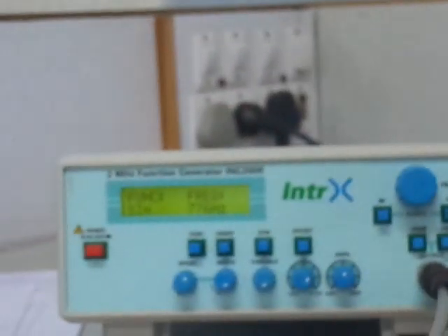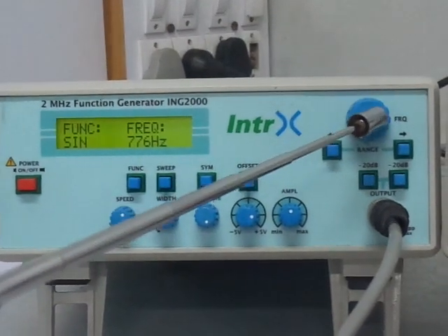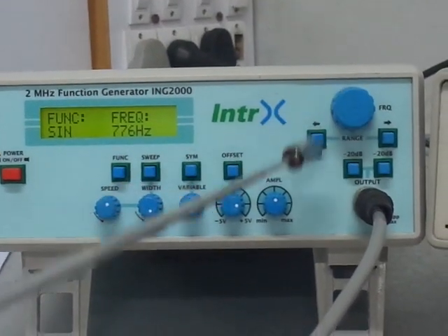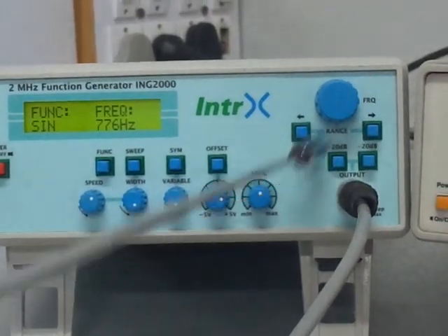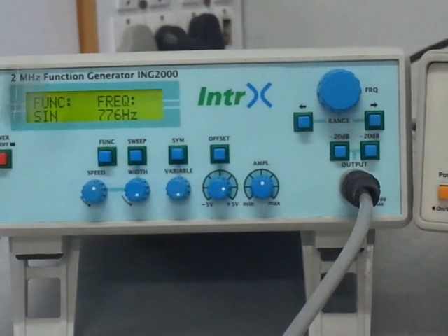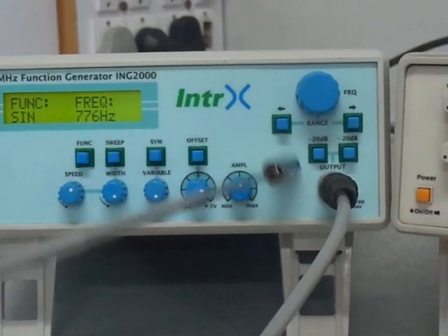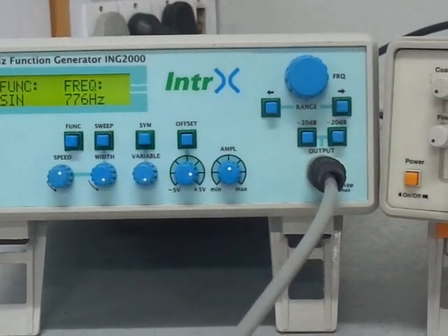Now we are going to take the measurements one by one. Let us start. This is the instrument. By using this knob we are going to vary the frequency. By using these two knobs we are going to select the range. By using these two knobs we can attenuate the input signal, meaning we want to apply a 1 volt peak to peak input signal. By using this terminal we have connected the input signal to our circuitry.